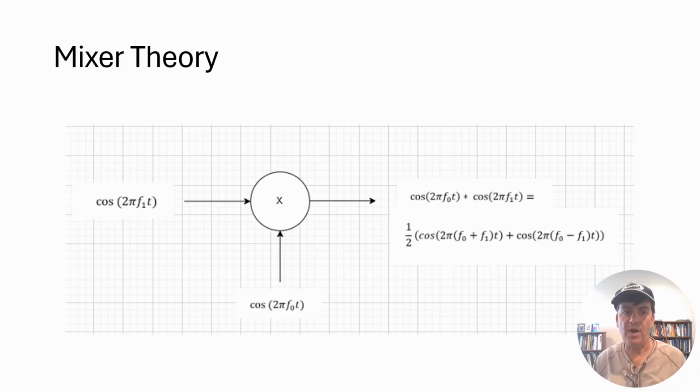The LO operates as a fast switch rather than a linear amplifier. Because Gilbert cell mixers are fully differential, provide conversion gain, and offer good port isolation, they have become the classic active mixer used in RF integrated circuits.